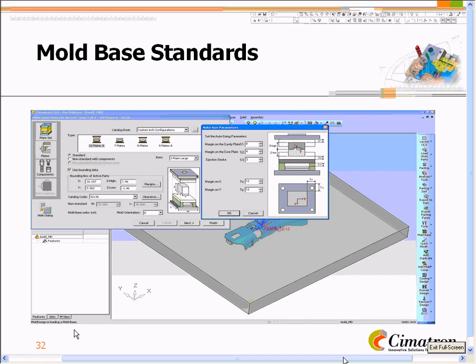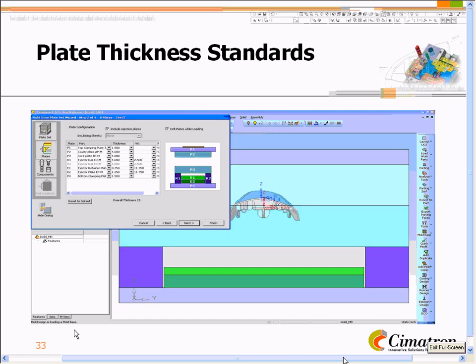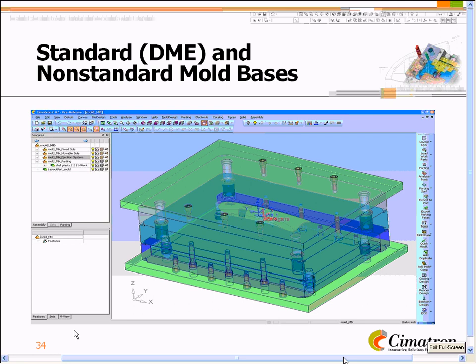You can put in his offsets or gaps on parting line, or even create an overlap condition if he's going to direct cut the A to B plate. But what's the best size? Well, here, if this is something being done in the quote, you can see just throwing the part in and then quickly getting a mold base around it helps generate the correct size. But it's going to be based on the size standards that you as a shop work with.